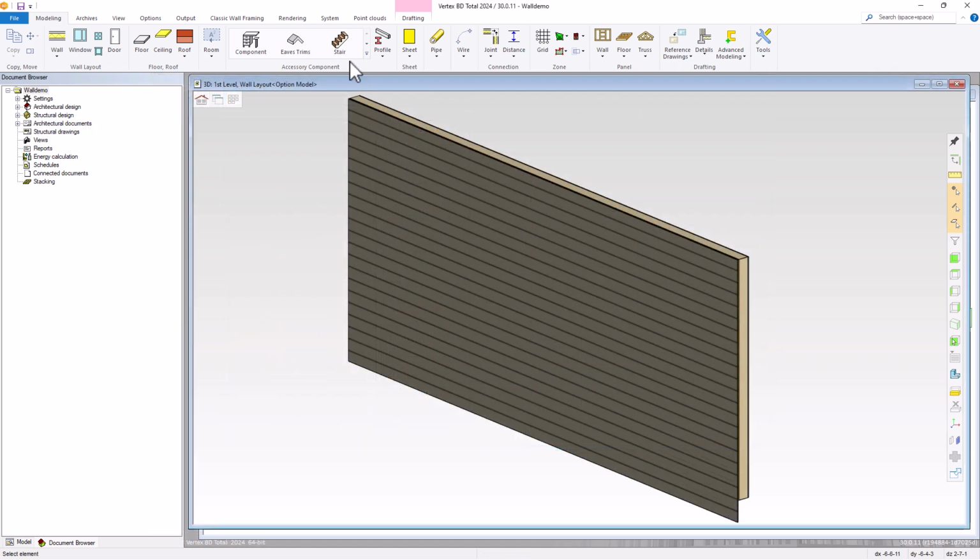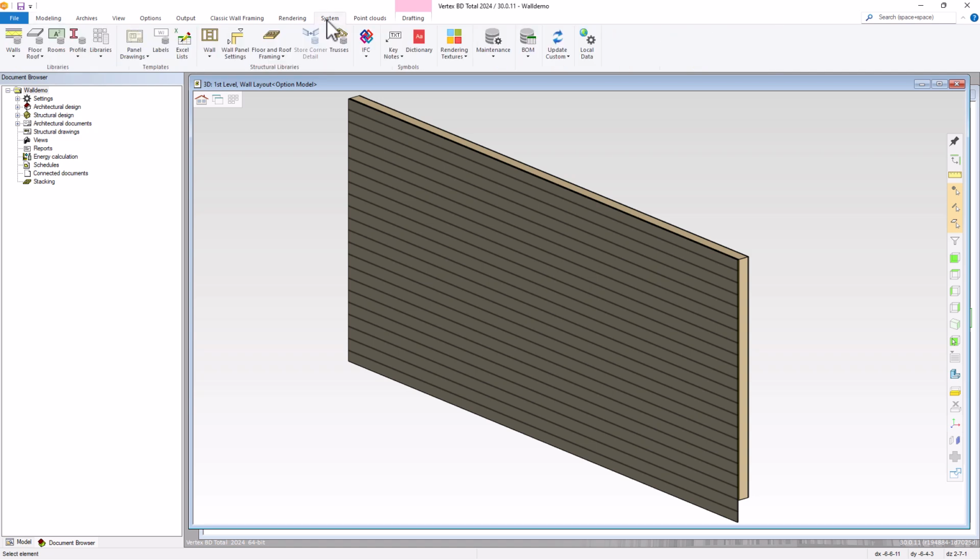Let's start by creating a new wall type first. It is not necessary to create a new wall layer or wall frame tool if there are system versions that exist and apply to your new custom wall. For this tutorial, we will cover the process for creating each type. As mentioned earlier, before creating a custom wall type, layer, or frame tool, a custom library must exist or must be created first if one does not exist.